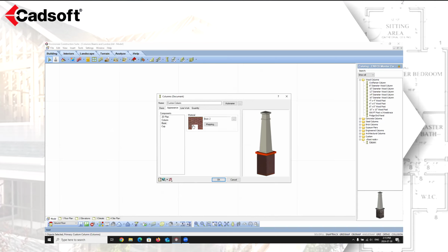Now, when you import a SketchUp block, it is going to have a mapping set to be predefined. So under mapping, the texture mapping is predefined. This just means it's using whatever SketchUp had defined. And since we didn't have anything defined, it's not really scaling this or creating it in any way around that face. So let's let Envisioneer map it. So instead of being predefined, we're just going to say face. We're going to say OK, and it's going to change the mapping of that to match what Envisioneer would use.